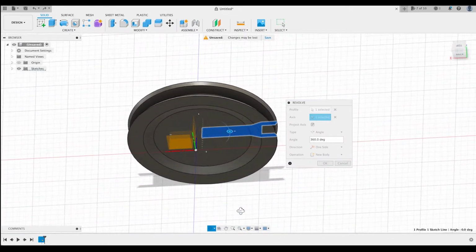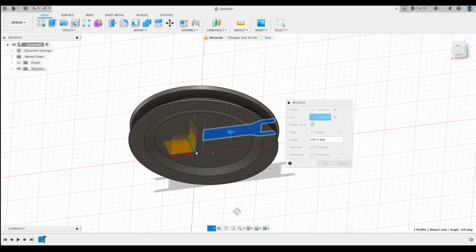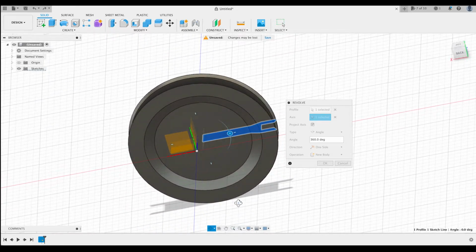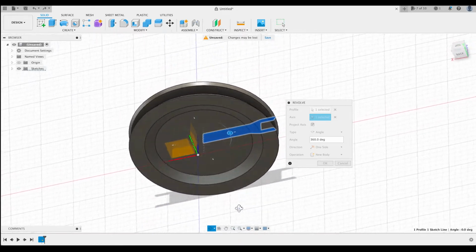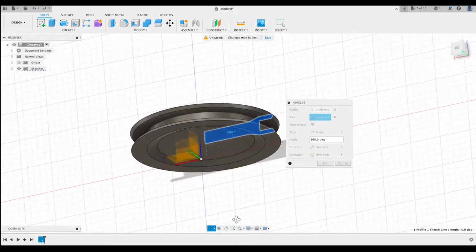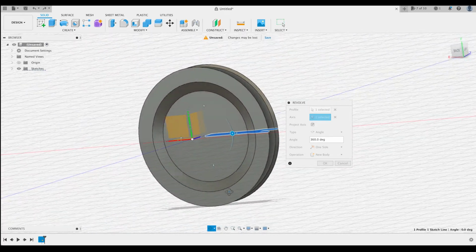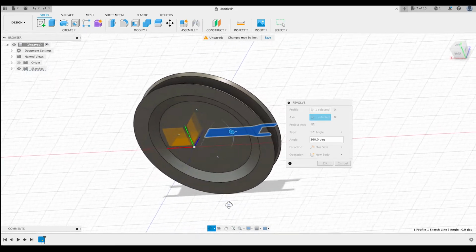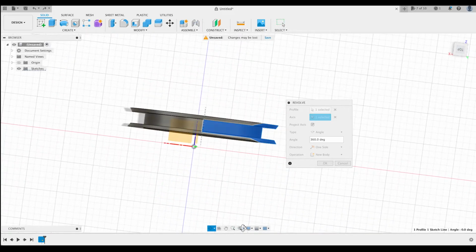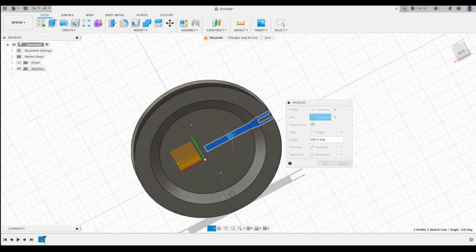So if you make your object away from an axis line, it gives you the opportunity to either rotate it around the axis or rotate it around the axis of the body itself on one of the edges. And so now, using that profile, I've made this very simple little pulley wheel. So what we're going to do now is make our own hole and put a flange through that as well. So let's just click off of this,